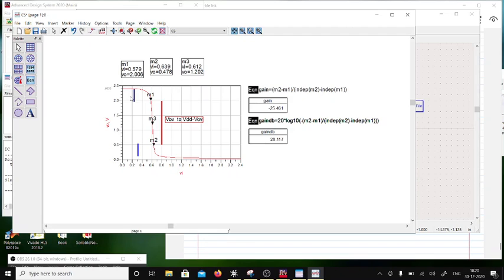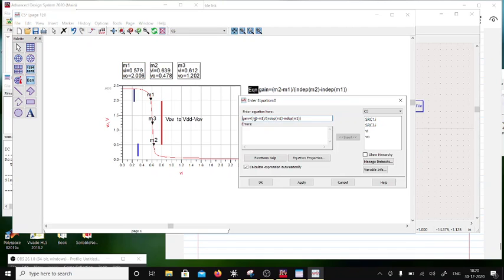Okay, so you understood that if I reduce W by L, then my overdrive will go up, and this swing will go down. So this is the price I have paid for improving the gain. The other price I have paid is the input voltage range Vi, which will be basically independent of M2 minus independent of M1. Okay, so the input range.